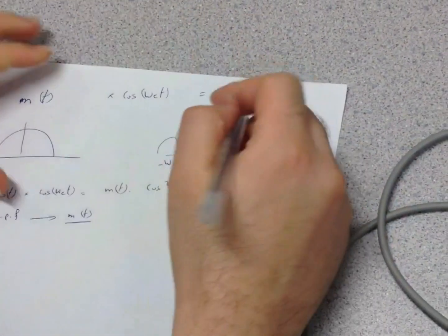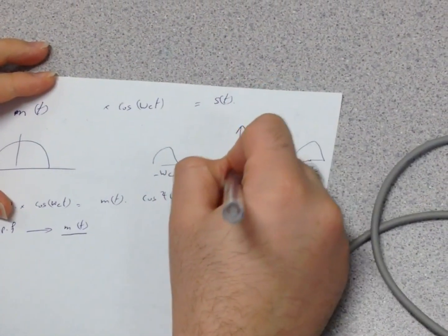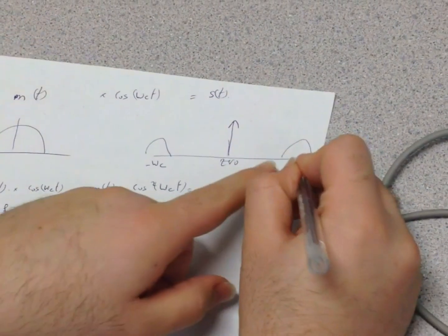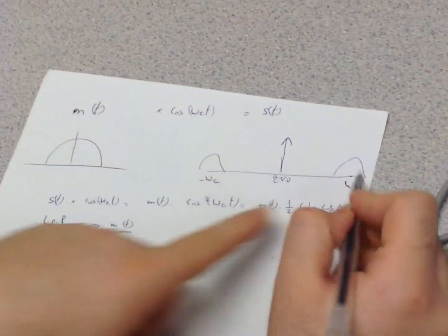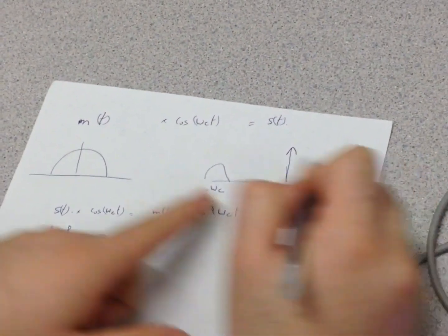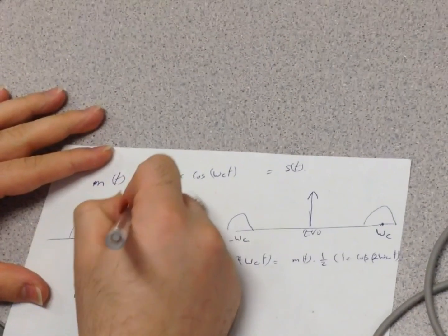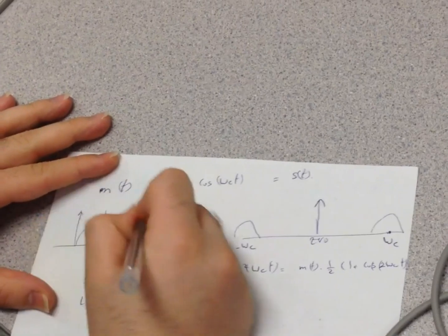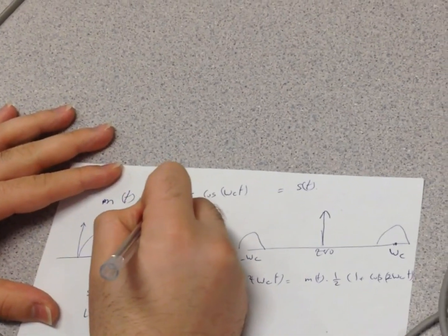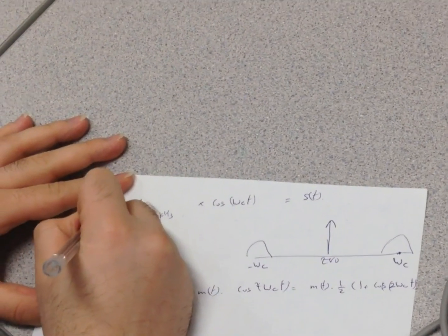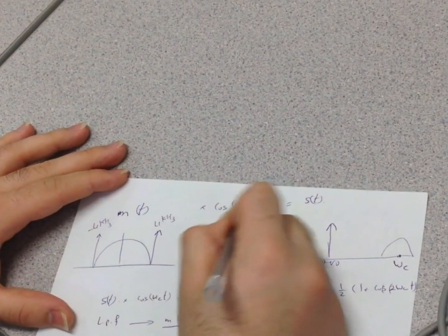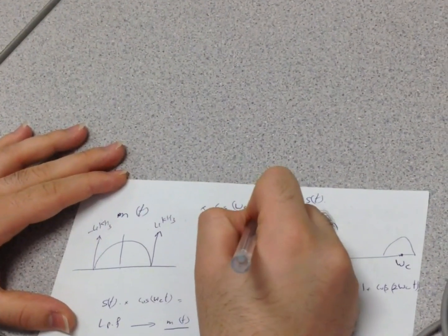This is the baseband 0. So my message, instead of being at baseband, is now at passband here and here. My message in this case is 4 kilohertz, so it appears at 4 kilohertz here and minus 4 kilohertz here, multiplied by my carrier, which is 64 kilohertz.